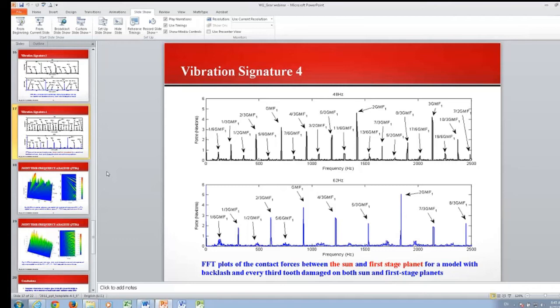But in my case, what we care about the most is if there's a defect of the gear teeth, how these defects affect the vibration pattern of our whole system. Because we have the sensor, right? The sensor is usually installed on the bearing location or on the gearbox.